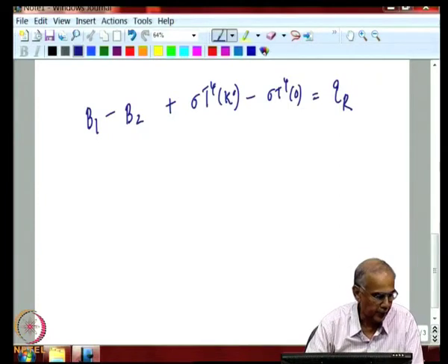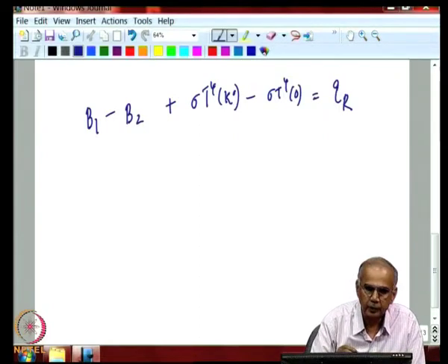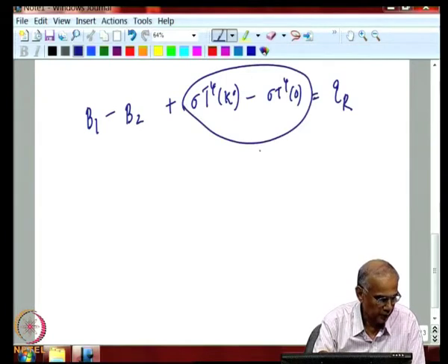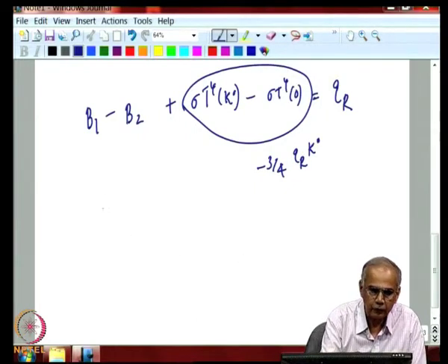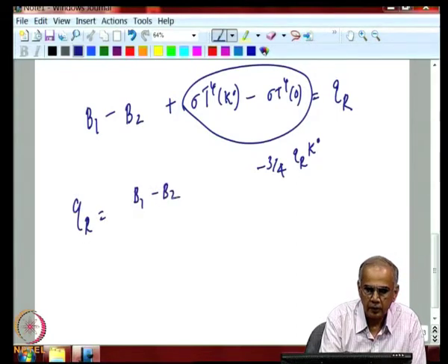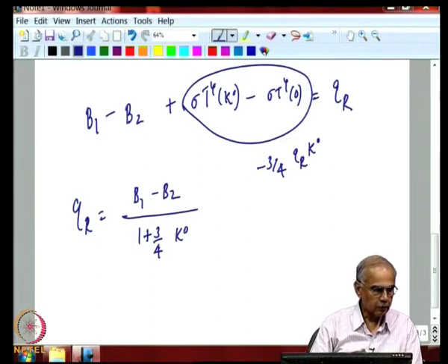And we know from the previous equation that this is nothing but this term, which can be written as, and therefore, we get this result that radiative flux is 1 plus 3/4. This was already obtained by the kernel approximation. We are rederiving it for the thick limit.